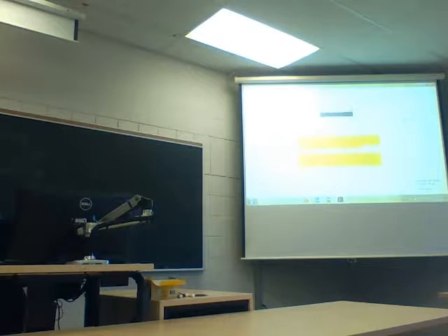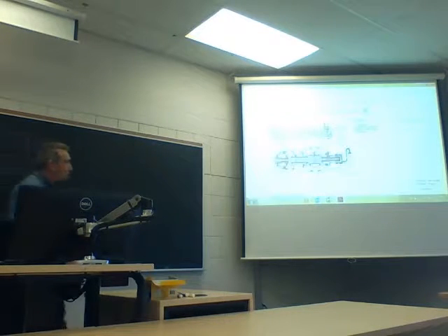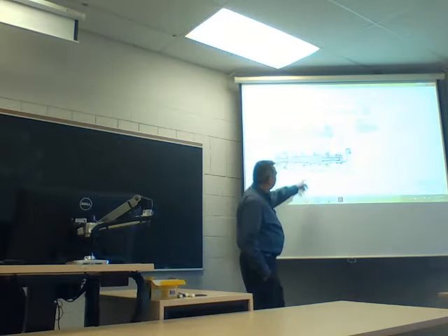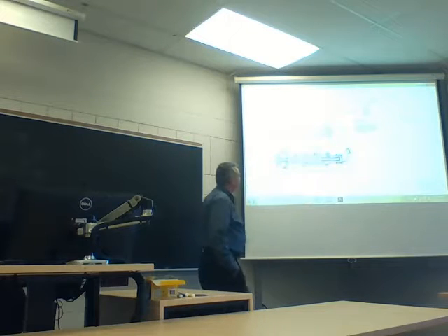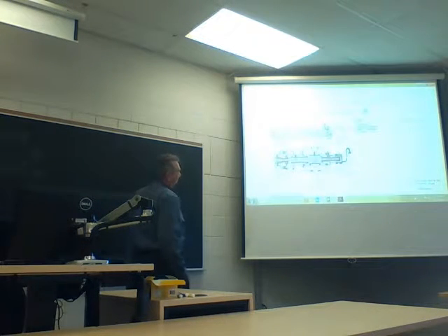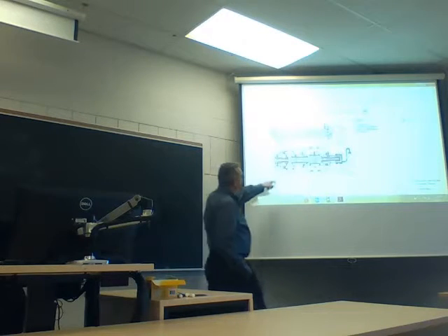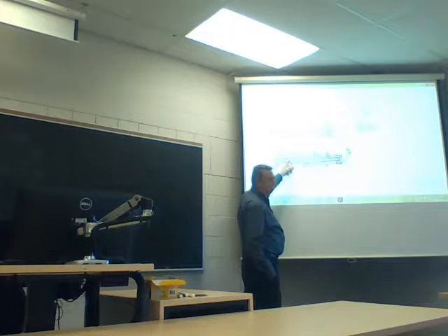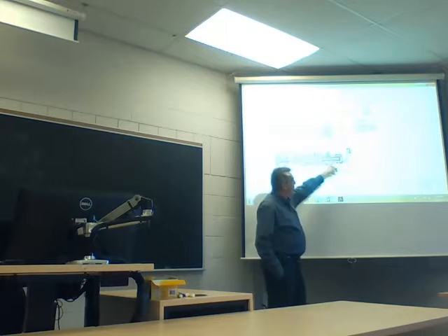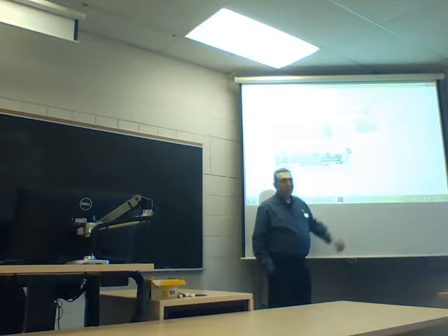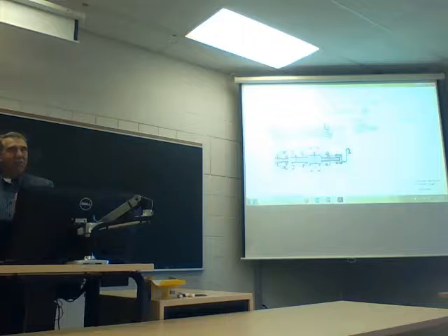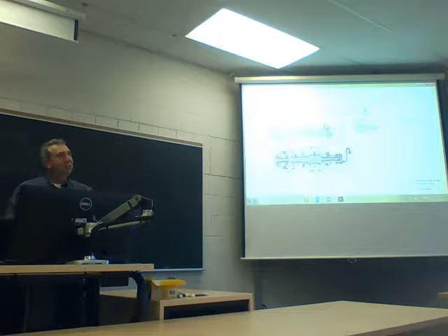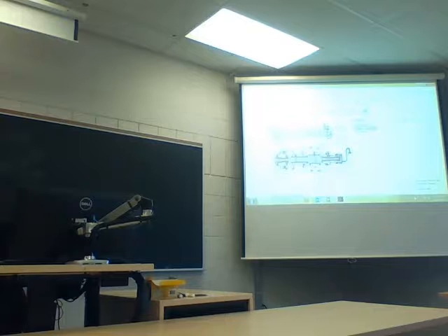And I think we can go to the picture and explain it. I think that's a really bad picture. So first stage here, we've got a double acting cylinder. See how we got it that way? And then we can follow the air, which is really going to be difficult to see. You're going to find that it comes into our second stage, which is here, and then it's going to go back around to our third stage, which is over here. See how that balances the compression out, so that when we're coming this way, we've got the same work as we're going that way. So it's nice and smooth, really smooth.